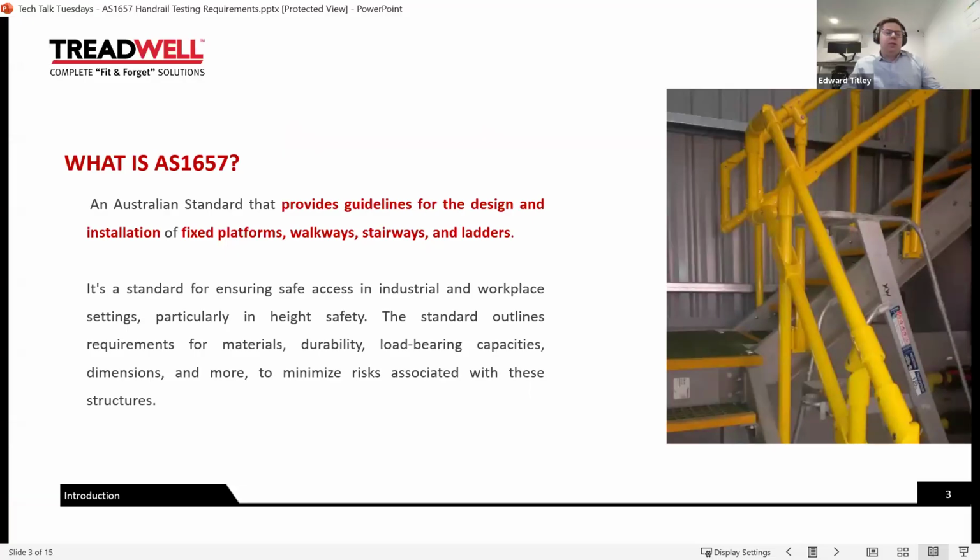So this is not public walkways or boardwalks or that sort of thing. Boardwalks should be AS2156. Public walkways typically AS1428. This is back of house maintenance type stuff. So it could be rail stabling yards. It could be access in a sewage treatment plant for personnel. It could be on a mine processing site. Something not accessible to the public is typically what AS1657 is applicable to.